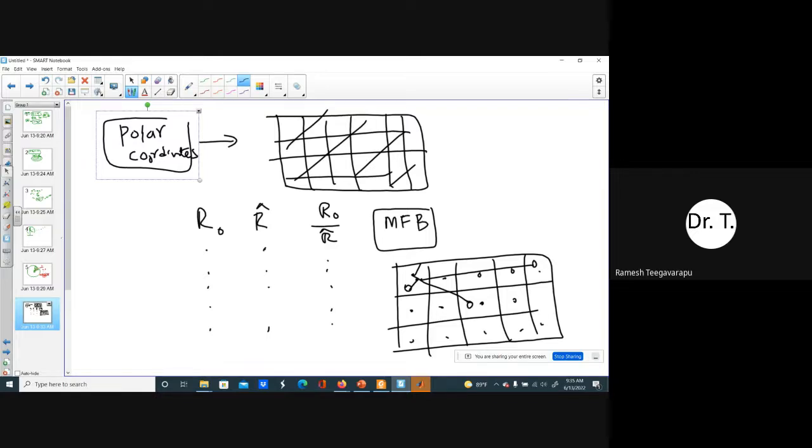The other way of correcting the local values is what we call quantile-based correction. You get the CDF, that is the cumulative distribution function, plot of your rain gauge data, and then you get the appropriate probability value for the radar also, and then you go back and get the corresponding value from the CDF so that you can actually correct the radar values.